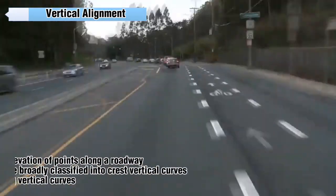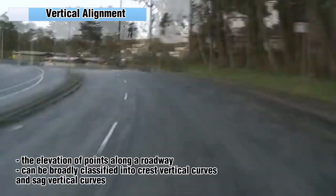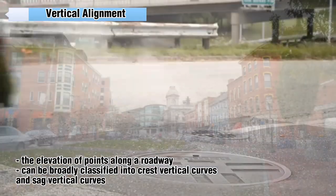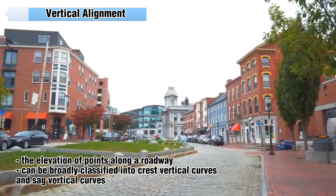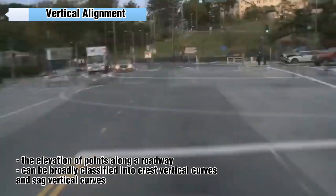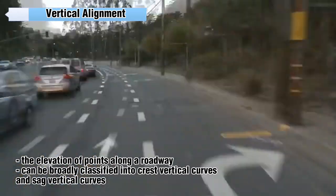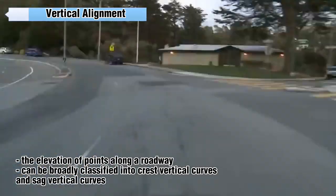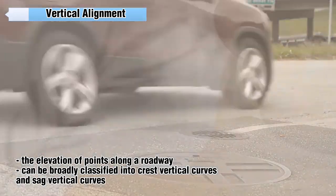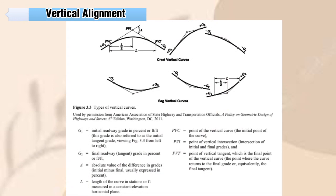Vertical alignment. The elevation of these roadway points is usually determined by the need to provide an acceptable level of driver safety, comfort, and proper drainage. It can also be broadly classified into crest vertical curves and sag vertical curves, and note that the distance from the PVC to the PVI is L/2. Here is the illustrated form of the crest vertical curves and the sag vertical curves together with the meaning of each term.